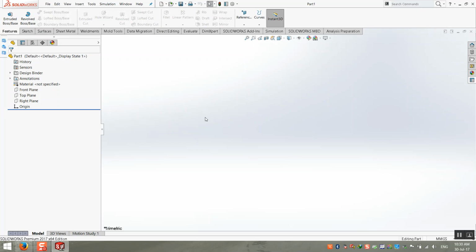In stress analysis, we put all conditions in the computer for the part. Apply material, it's very important. And apply the points of fixation. I fix it here from this point and this point. Apply load and load position. I will apply load here.